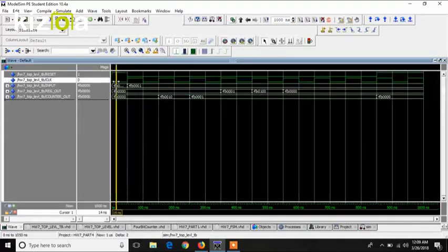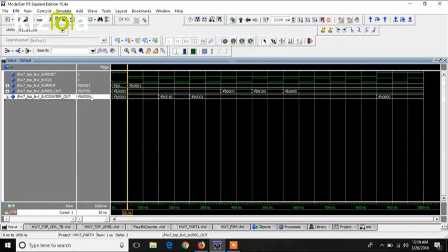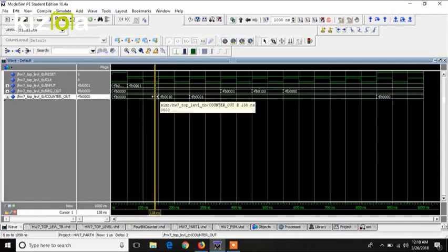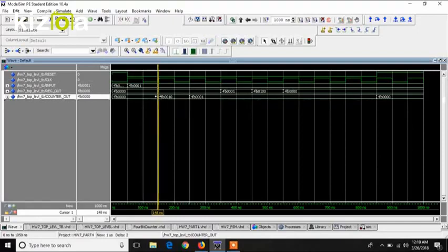So here we are, the reset is 1, nothing is happening here. And then it hits the state 0. In state 0, it's supposed to clear the register and reset the counter, and it does. So at the next clock edge, that's going to be state 1, then it's going to increment the counter by 1, and it does.